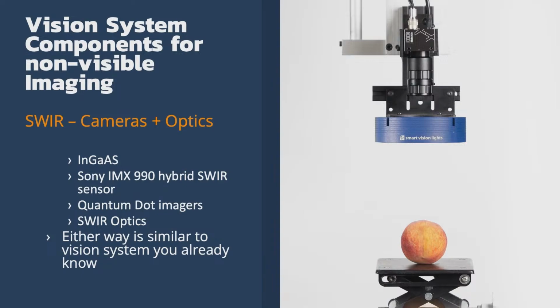So in this case, we do need a special camera, and shortwave infrared cameras are typically very expensive. Historically, they have been what we call InGaAs, or indium gallium arsenide, and an InGaAs sensor is a different manufacturing process than a silicon sensor, and that has made them very expensive. But two recent breakthroughs have brought the cost of SWIR imaging cameras down. One being the Sony IMX 990 hybrid sensor that I previously mentioned.